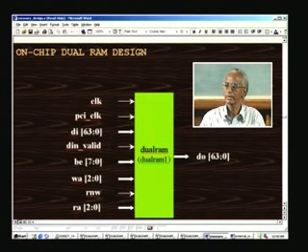This is also something we can derive from one of the PCI signals, and there are many more PCI signals. We are not considering all of them at this point of time. You can bunch all the other requirements into what is called a data invalid. So when this data valid is indicated here, and once again there are 8 bytes, and each of these bytes, when valid, will be indicated by the BE signal, which stands for byte enable. This is also a PCI signal, and there are 8 bits totally, and whichever is made 0,